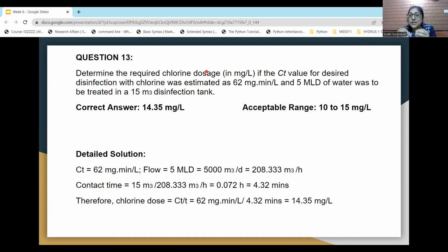So chlorine dosage is that amount of chlorine that is required to meet the demand of disinfection plus the requirement of residual chlorine. That is, the reactions required to form some residual chlorine. Both together, the dosage of chlorine that helps us acquire this amount, is called the chlorine dosage. We can come to the further explanation in the following slides.